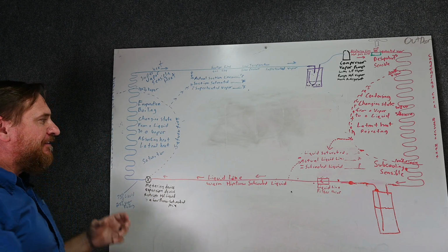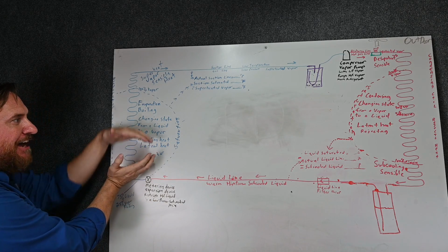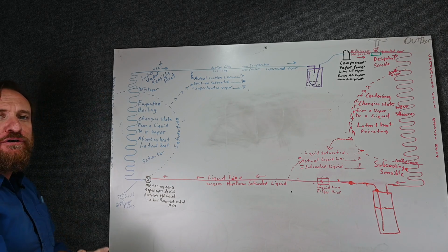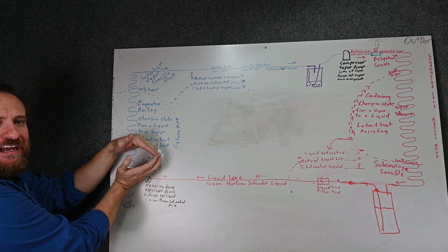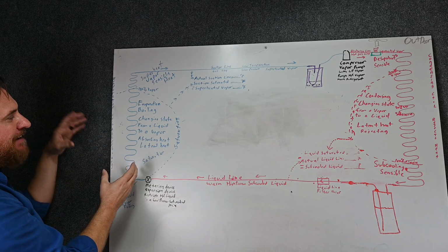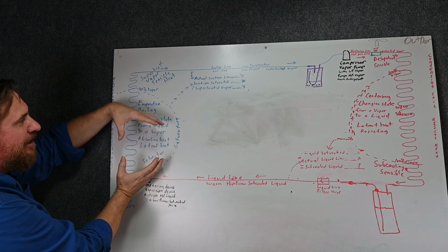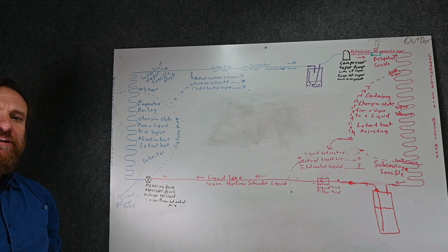On top of that, we have the factor of the temperature of the air and the humidity of the air affecting how fast or how slow that refrigerant boils away. If I have a very large heat load, my refrigerant can boil away down here very quickly and I have a whole lot of superheated vapor. And if I have a very low heat load, I could end up with a very small amount of superheat and a whole lot of saturated liquid mixture.